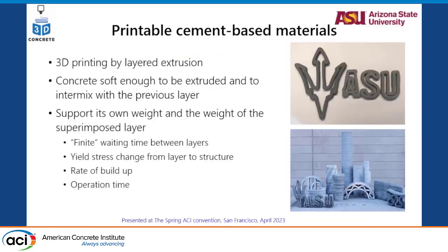These are some printings that have been done in general literature. So, what's a printable cement matrix? Something that can be extruded. Pumping was not a requirement here because we didn't pump it, but again, extruders should be able to pump it out of the nozzle, and it should be stable enough that it will withstand its own weight, so more layers can go over it. For printing, we need a cement mortar matrix that's soft enough for extrusion but stiff enough that it can handle its self weight.